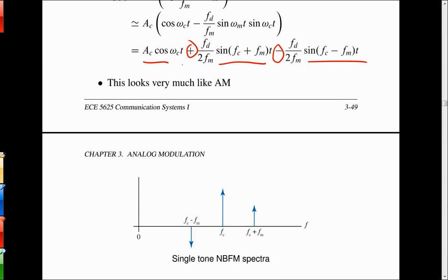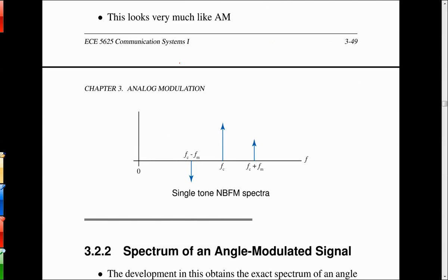So it's just emphasizing that. But the narrowband FM amplitude spectrum on the spectrum analyzer doesn't really look any different than AM does. You would see a strong central carrier and two very weak sidebands, and nothing else, and you wouldn't be able to tell the difference unless you're paying attention to the phase, which the spectrum analyzer doesn't do.